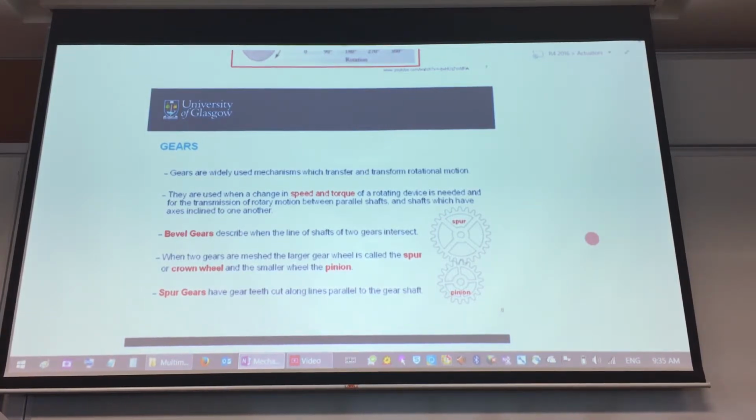Because when you build the Lego, you'll be building it in a certain way, but it's not a trial and error way. It's this knowledge that you have to apply. You'll be talking about gear ratios, for example. Why did you choose this smaller gear to a larger gear? What kind of gear ratio will you derive out of it? What sort of torque is applied when you design that gear ratio? You need to present that sort of calculation so as to not design it by chance just because it moves, but you know that as it moves, what kind of rotational speed and what kind of torque is being applied.